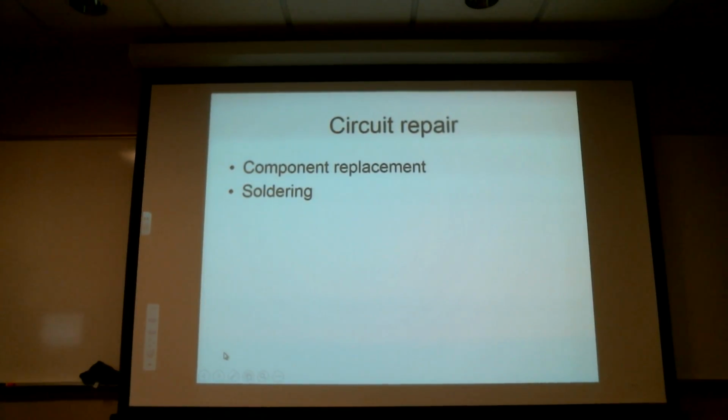Apparent power is volts times amps. True power, that's what you're getting, that's what actually, the saw that's cutting. So true power in a DC circuit will equal apparent power, but in all other cases it'll be less than apparent power. Okay? So reactance of some kind is going to cause you to lose some efficiency.